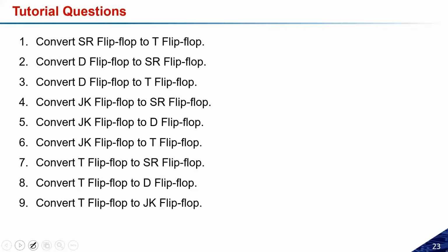Okay, but if in the problem it is given that you have to make the converted flip-flop hazard free, in that case you have to use the redundant pairs as well, which we have already done before. We know how to remove the hazards in the logic, so you have to apply all those rules here as well. Okay, so please try to solve the rest of the problems, and that will help you to understand the actual things.